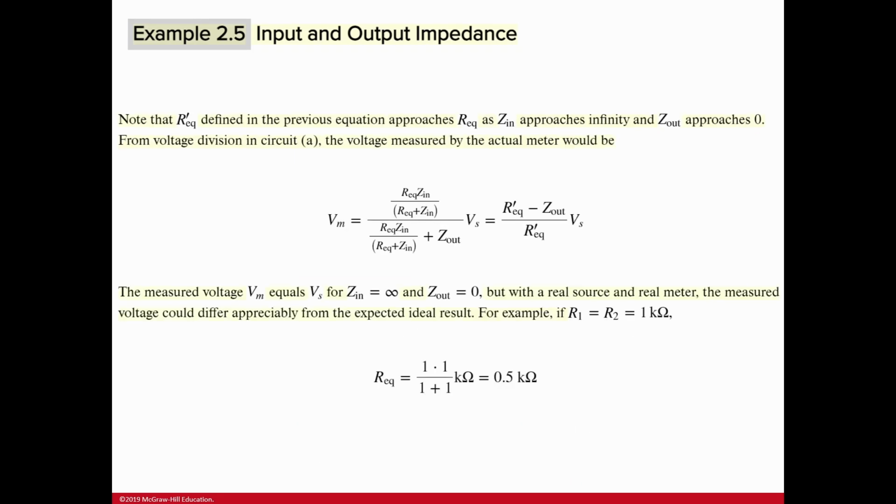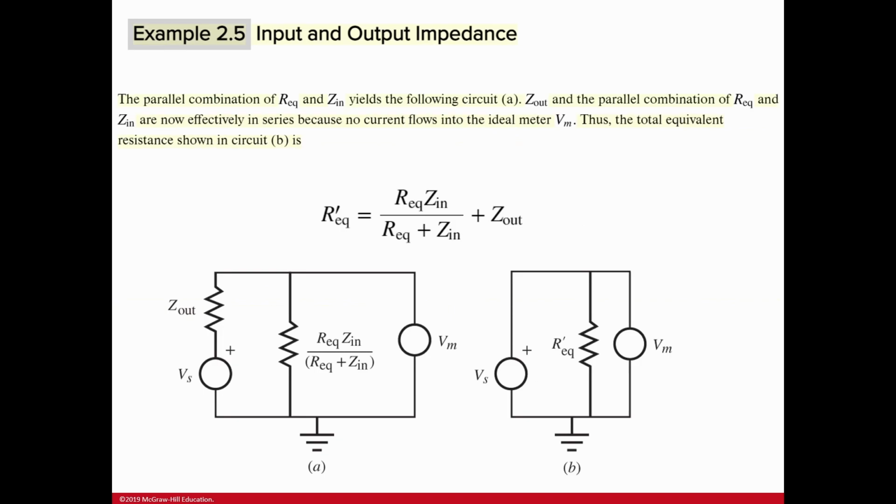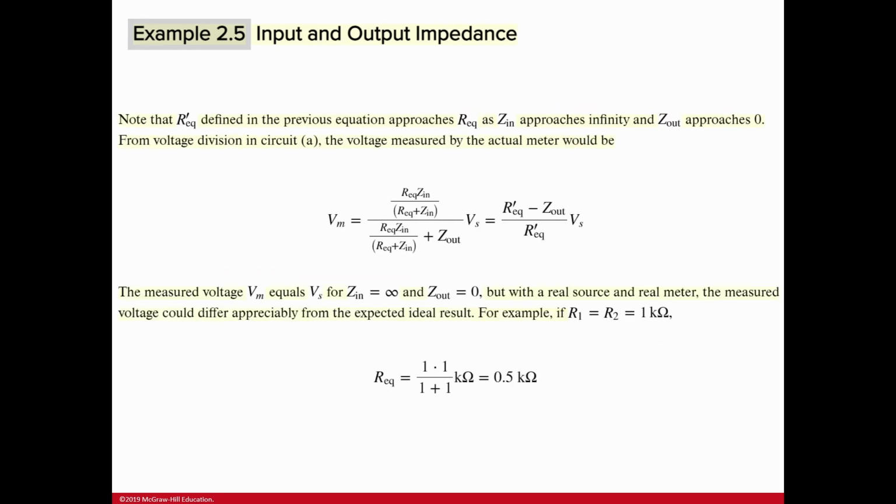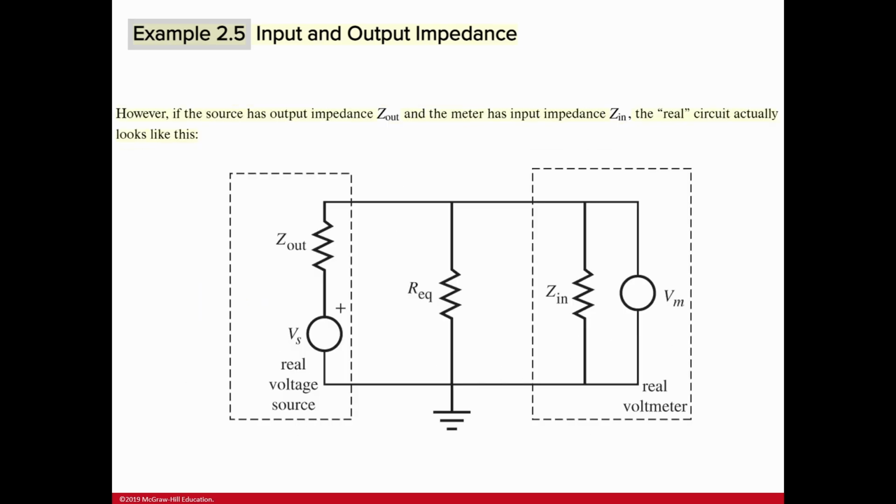Because we want to get a voltage here, it's actually a voltage divider for these two resistors. So the proportion is this equivalent resistance to the overall equivalent resistance. Okay, yeah, but this is very complicated. How to check if this is correct or not? We know ideally Zin is this, the input impedance of the voltmeter is very high, so we say it's infinite.